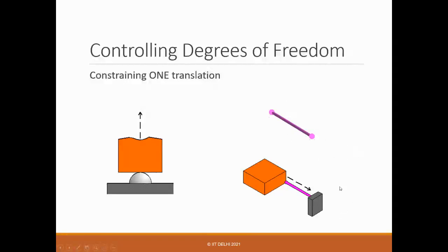So here also, I think what is important is, if it's not a point, then what is the constraint line? And along the longitudinal direction, the stiffness is much higher because of its material. So it's EA by L. Longitudinal stiffness, axial stiffness, is much higher than other stiffnesses.